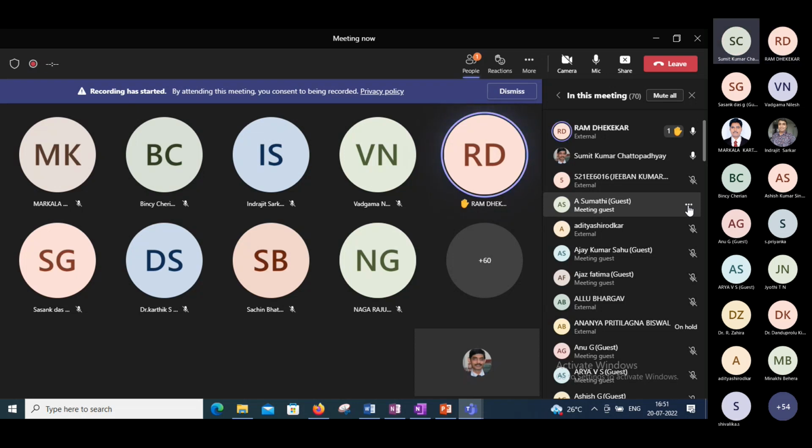You would need 4 switches connected in series, and that has to be operated, maybe at 5 kilohertz, which is not possible to achieve. As I said, 500 hertz is the limit. On the other side, you divide the DC bus into 4 parts, 2.5 kV each. So in a cascaded H-bridge, say you have 4 cells. So what will happen?